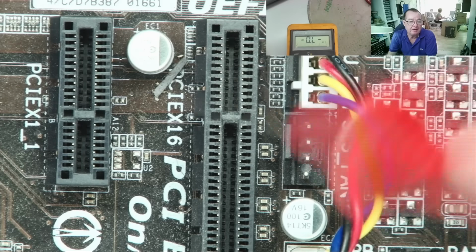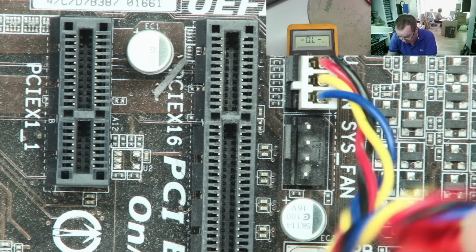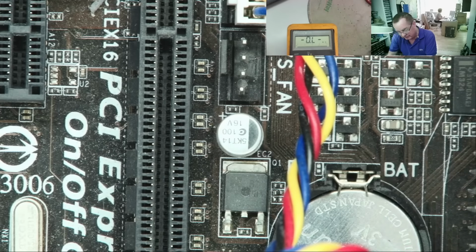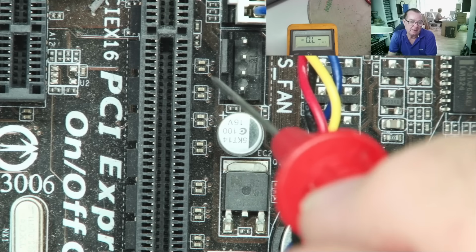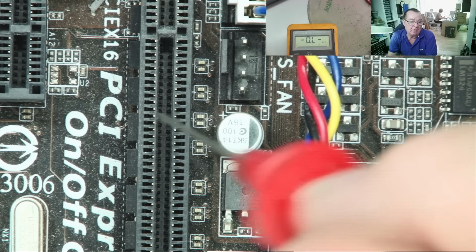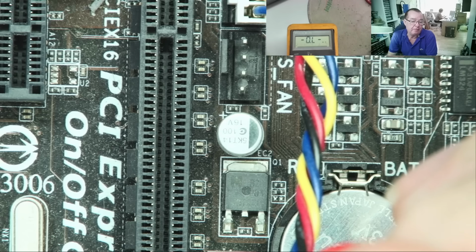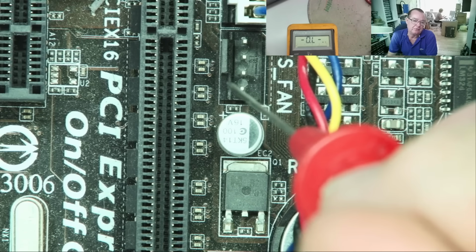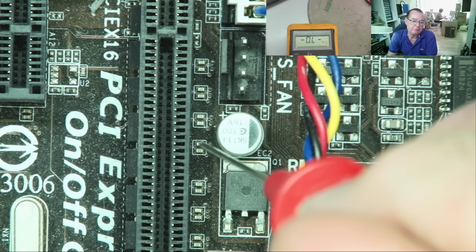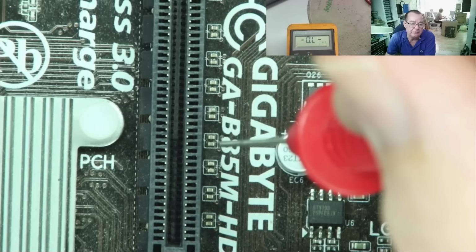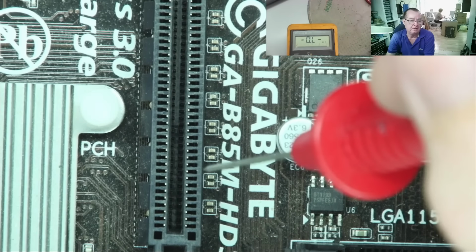Just to prove that point then, here is a PCIe slot on the motherboard, and you can see there are capacitors on each lane, each PCIe lane, but only on one side of the slot. So this is exactly what I was trying to demonstrate, that all of the lanes or pairs have capacitors, just half of the capacitors on the motherboard and half on the graphics card. So again, we can see we have 1, 2, 3, 4, 5, 6, 7, 8, so that logo, 9, 10, 11, 12, 13, 14, 15, 16, okay?